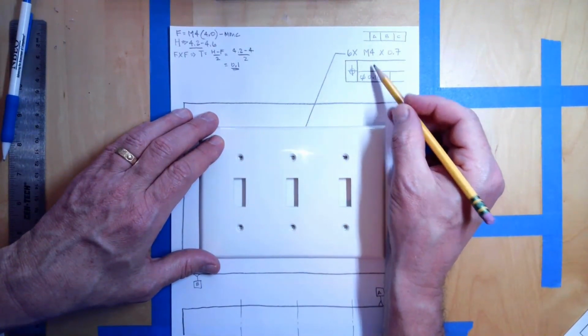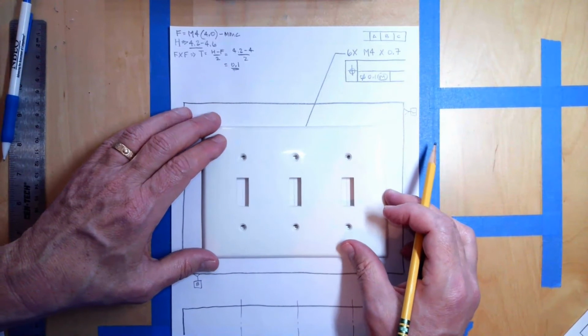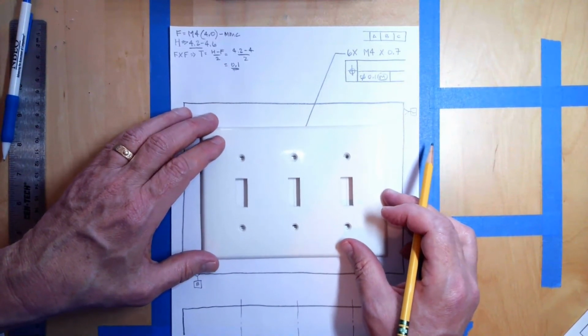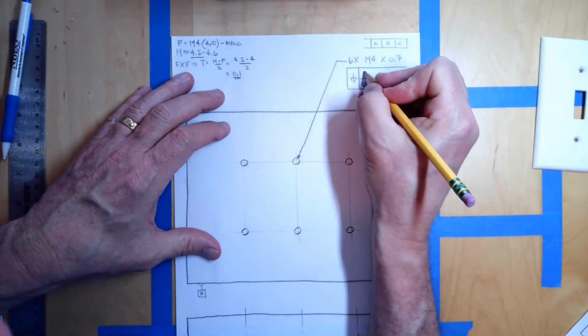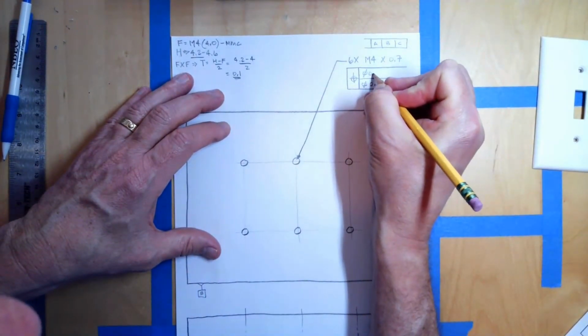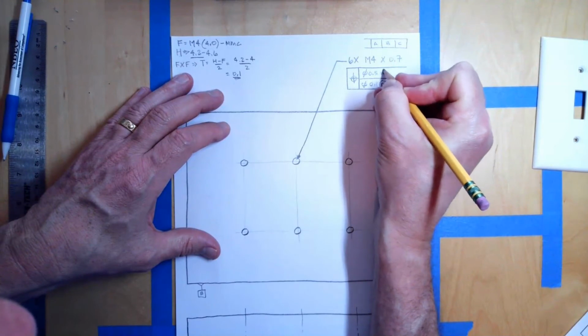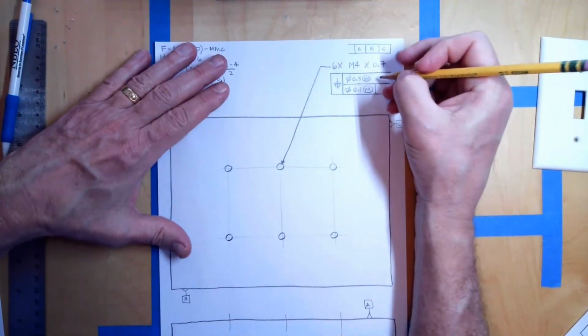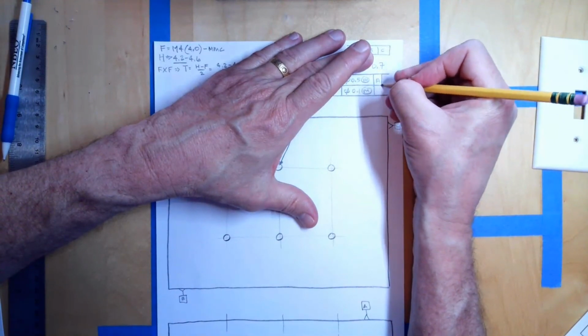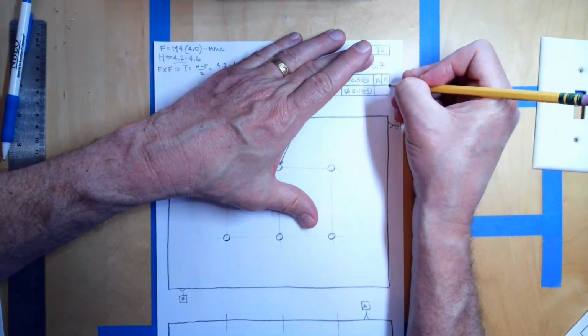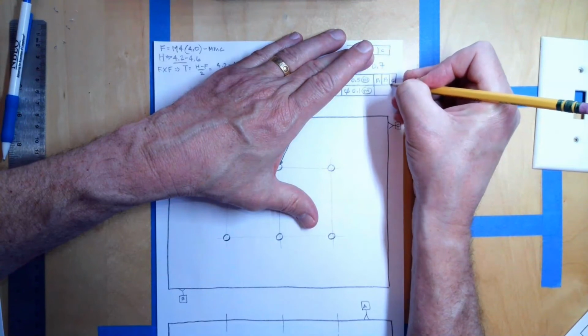Remember, the pattern locating tolerance zone has to be more than that one. So I'm going to say that this can be 0.5 millimeter. That's pretty good. The tolerance of 0.5 at MMC. All right. And now relative to what? This one is A, B, and C.